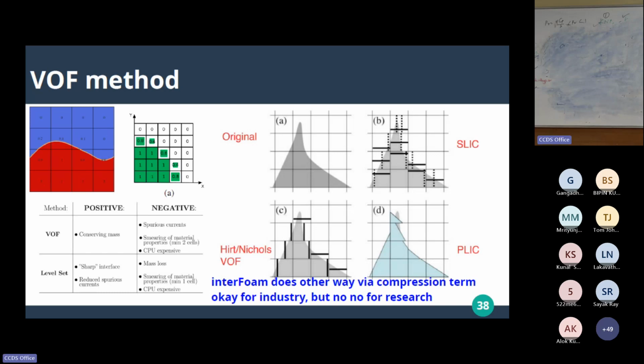So to summarize, even before beginning, what is interFoam? InterFoam never does this reconstruction procedure. Instead of that, it just smoothens the field. Alpha, whenever it is something like 1.6, can I really use some kind of Gaussian filter?